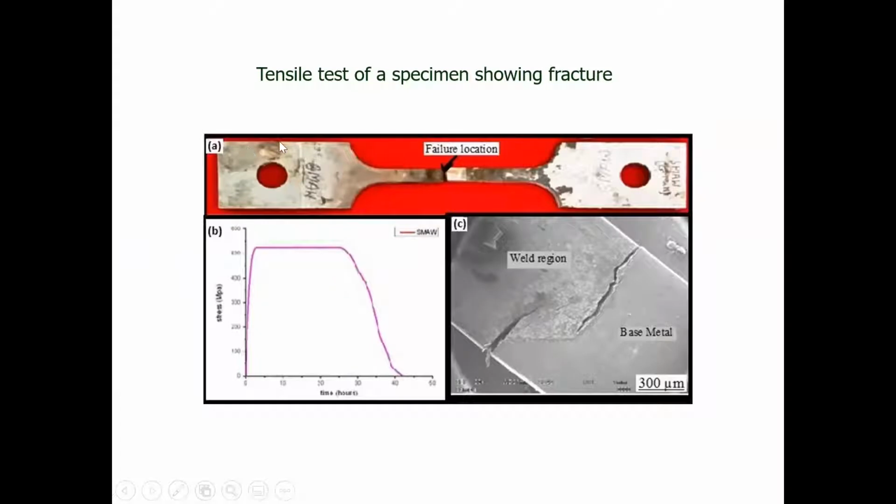And very often what we do is we make a specimen out of a metal. This happens to be a piece of sheet metal, and we cut out a groove in the middle, this shape. So we narrow it down, we make it thin in the middle and thick at the end. And these two holes here represent where we attach it to a machine to stretch the material. So we pull the sample in both directions, left and right. Because we thinned it down deliberately with this profile, most of the force we're applying is in the middle, somewhere between here and here. And if you pull it for long enough, it will fail somewhere in the middle between this point and this point.